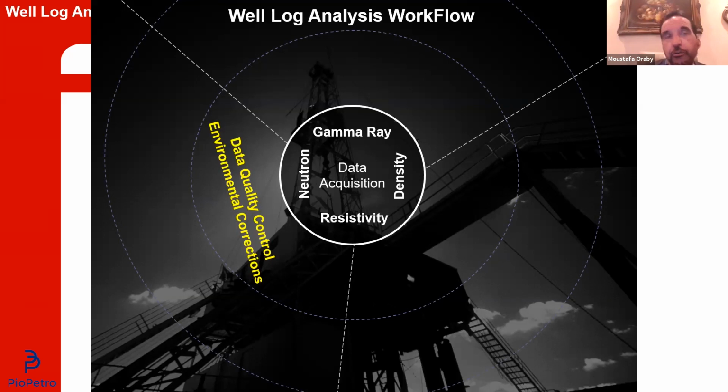For example, if you have a mud that you're weighing with KCl, or weighing with bentonite, or weighing with barite, whatever, these are not part of the API calibration. API calibration has a certain procedure and standard. Since you ran your tool in a different environment than the API environment, you need to do what we call environmental correction. Environmental correction has nothing to do with your reservoir.